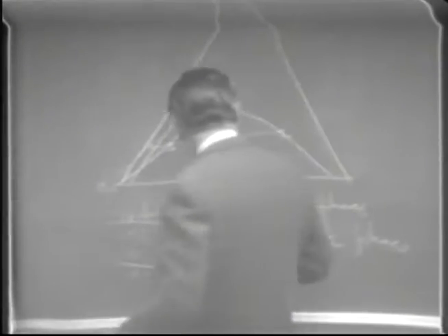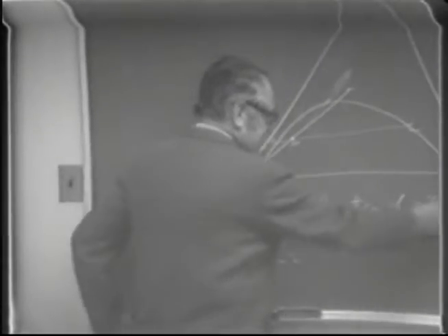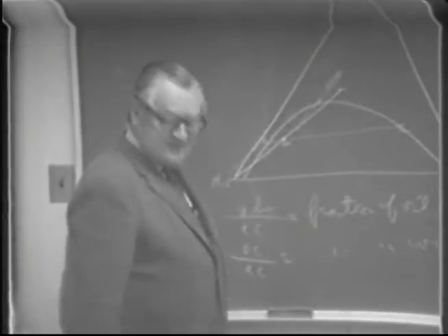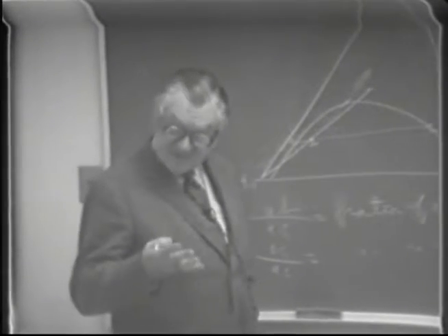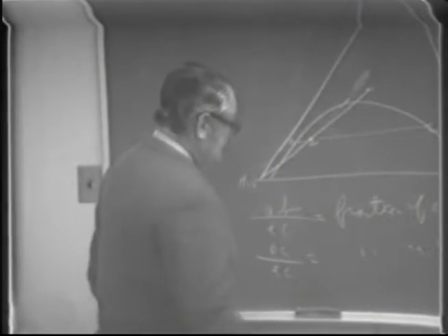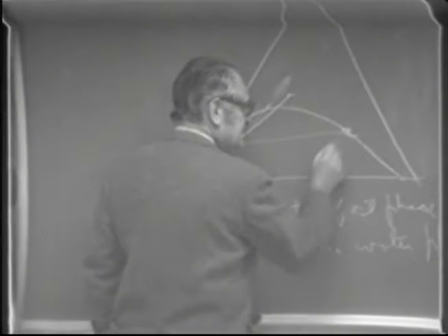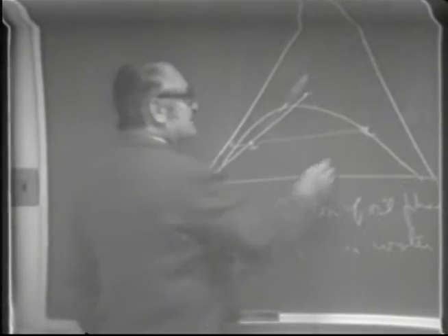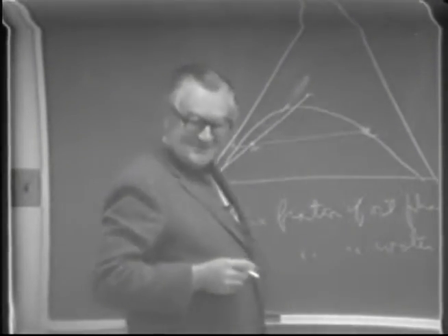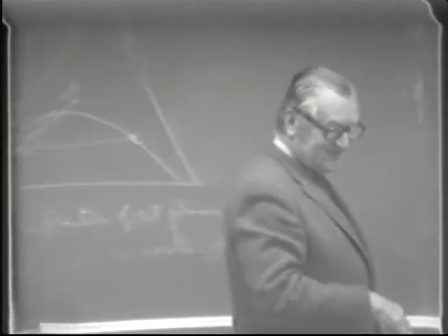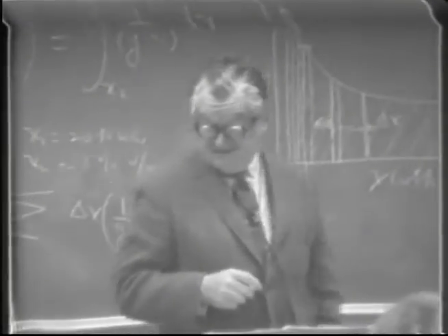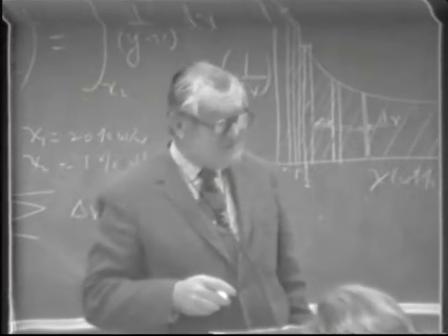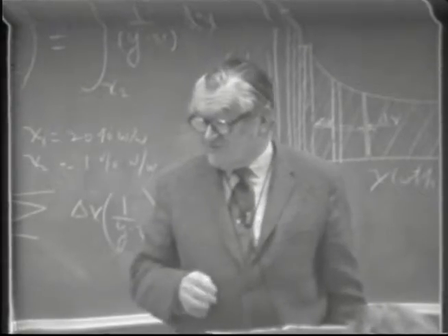And if you know the fraction, then of that total, it'd be just that fraction of the mass that represents the mass of that phase. Then you just read off here what the concentration of fusel oil is in there. So the concentration times the mass, of course, will give you the amount. And that fraction of the amount taken in the original mixture would be the percent recovery.